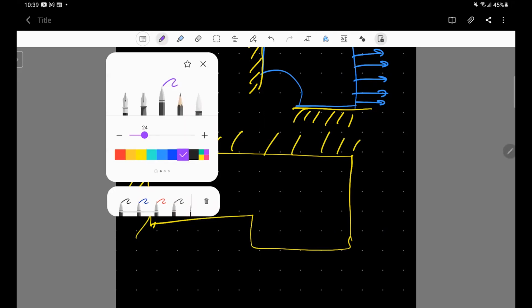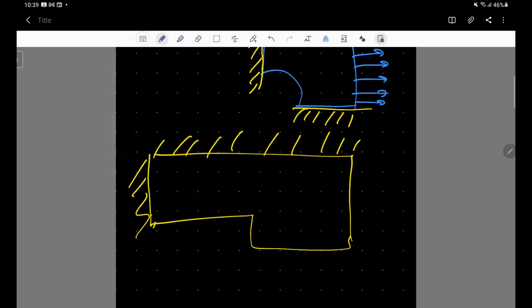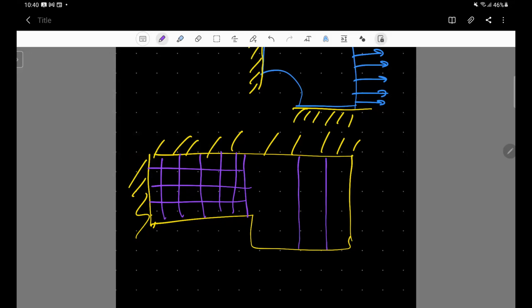On the fixed end you would like to use a certain mesh with a certain aspect ratio, and when you move on to the right hand side, you would like to use a much larger mesh size, since you assume that the stress variation in this region is quite insignificant, and you would like to use a larger element size to tackle this problem.